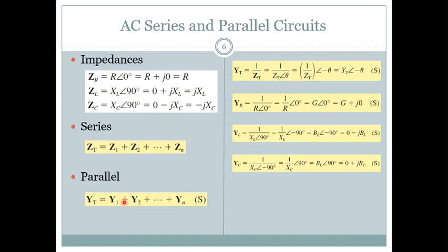So therefore it is easier for us to work with admittances rather than using the parallel impedance equation. So that is why we do that, but it is actually essentially the same. You can see that if you substitute the Z's in this equation, it is 1 upon ZT is equal to 1 upon Z1 plus 1 upon Z2, and so on and so forth. So it is essentially the same, but for easy operations, easy use, admittances are used instead of impedances.